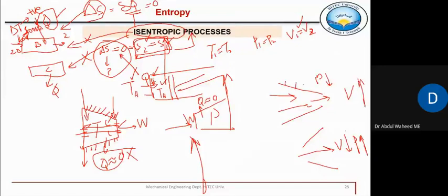And if we insulate this outer surface of the nozzle, it means we are making this Q, the heat transfer with the surroundings, approach 0. And here again, the friction between this fluid and the walls of the nozzle, that is a perfectly smooth surface, that this friction is also approaching zero means Q approaching zero.